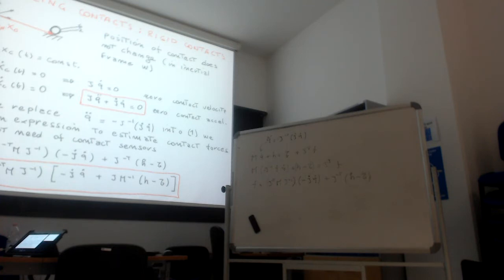So what we multiply for an acceleration that we get a force. What is the quantity that if you multiply for an acceleration you get a force? Inertia. Okay, in this case the force is an end effector force, so this will be the inertia seen at the end effector. We call it reflected inertia, the operational space inertia. But we will see in detail afterwards in the next lecture how it looks.